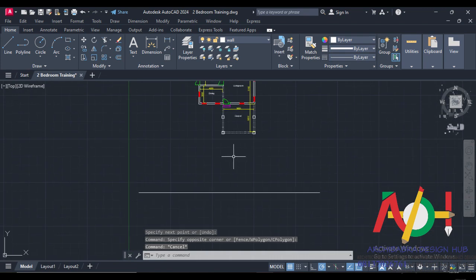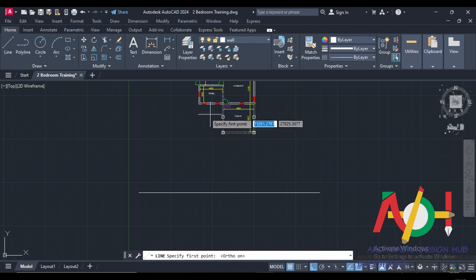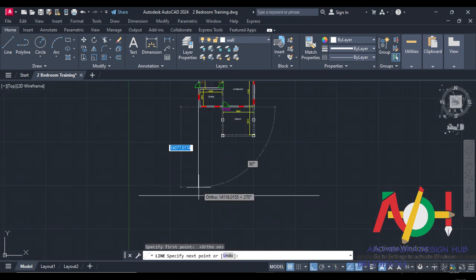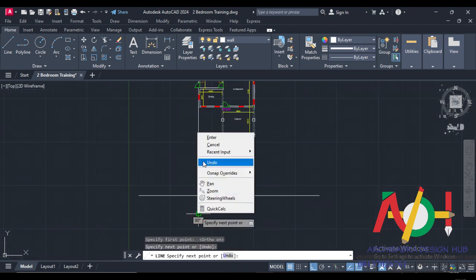So the next thing I'm going to do is to project. I'm going to be projecting most of this or all of this information I have here, the windows, the doors, and the walls. I'm going to be projecting it down here. So look at what I'm going to do. I'll pick my line tool, right? Then I'm going to put auto, so that I want the line to be perfectly straight. Then I'm going to start projecting this particular portion. So I'll project this down.